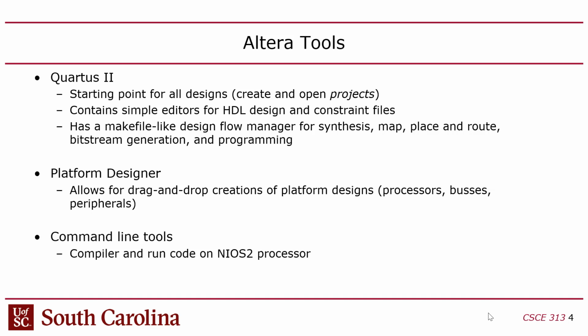Quartus basically is a tool that allows you to take Verilog code and convert it into a form where you can program the FPGA. That's essentially what it does. Now in this class, we're going to take that a step further, like we do in 313. Instead of having you use Verilog directly, and we will be learning Verilog in this class, but initially we're going to use something called Platform Designer, which is a separate tool, although it's still under the umbrella of Quartus. It allows you to construct a platform, meaning it's got a processor, a bus, and a bunch of peripherals in a system on chip.